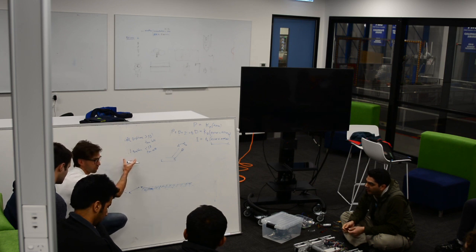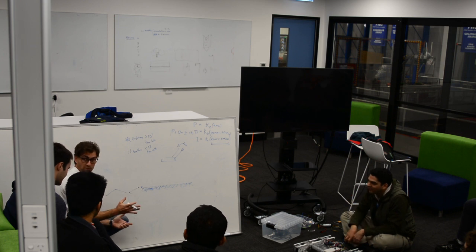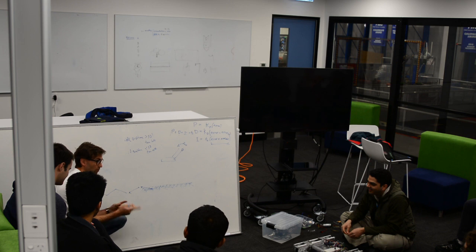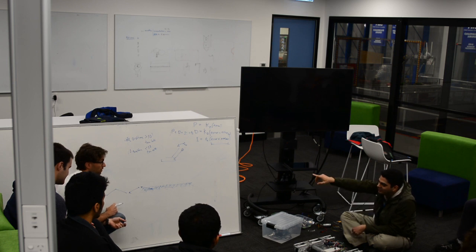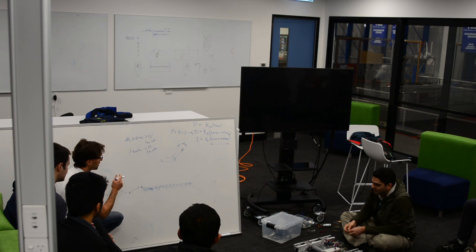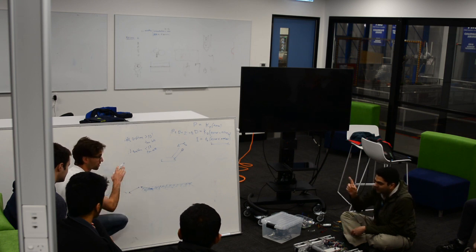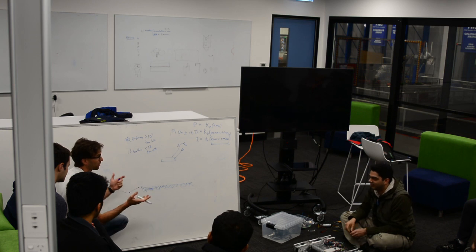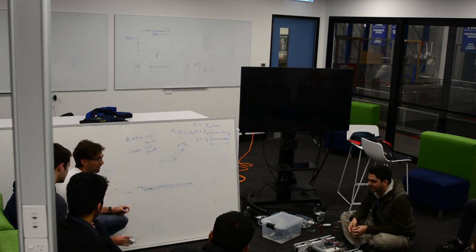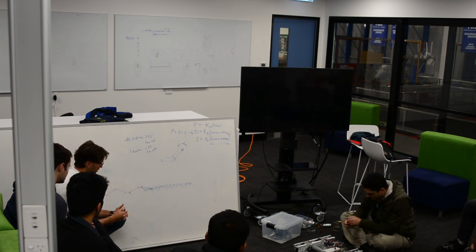Now this is essentially, what control system would we call this? It's a bang-bang control because we're in one of two states. We're either in the turn left state or the turn right state. You could certainly make it proportional, right? There's no reason you couldn't make it proportional as well. It works fine. Couldn't you just feed it 100 minus brightness to the left motor, and brightness minus 50 to the other motor? Exactly. And that's the simple way to do line following.